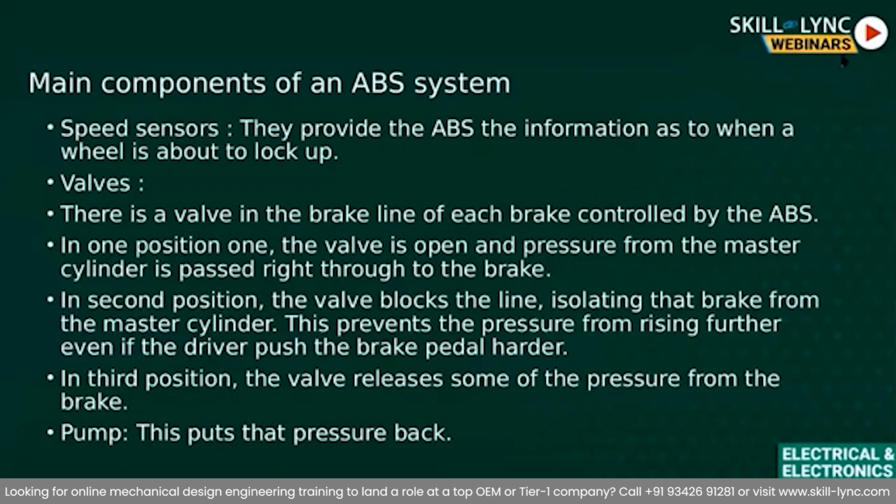If left unchecked, the wheel would stop much more quickly than any car could. The ABS controller knows that such a rapid deceleration is impossible, so it reduces the pressure to that brake until it sees an acceleration. Then it increases the pressure until it sees the deceleration again. It does this very quickly before the tire can significantly change speed.